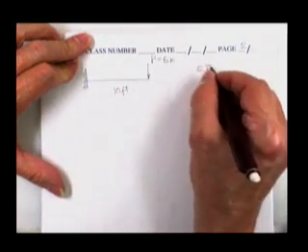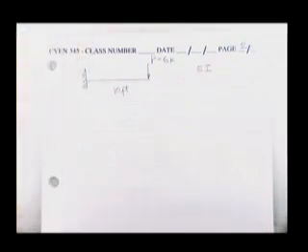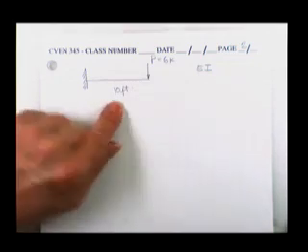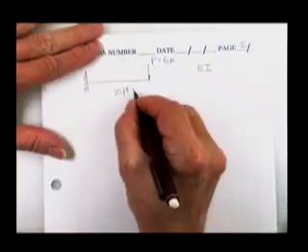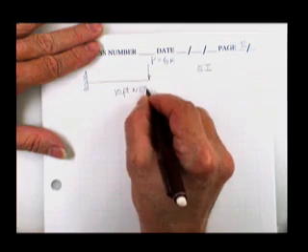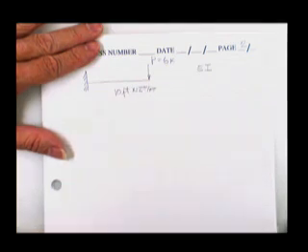The structure has the properties E for the material of choice, say steel, has a moment of inertia for a W12 by 40 wide flange, whatever it is, so many feet to the fourth. You're going to have to either change this to inches, or change this guy to feet. Probably most people go ahead and put in a 12 inches per foot before we get started. Make that length 120 inches.